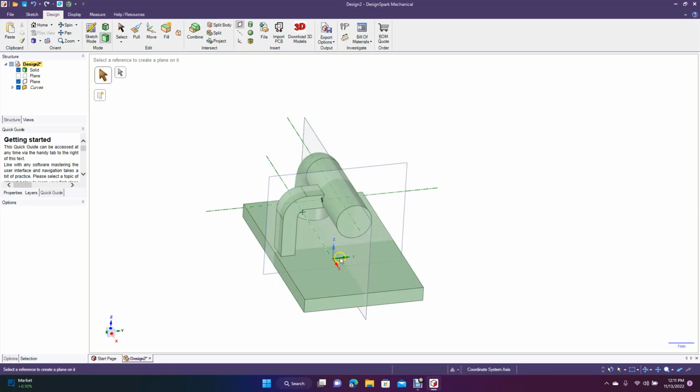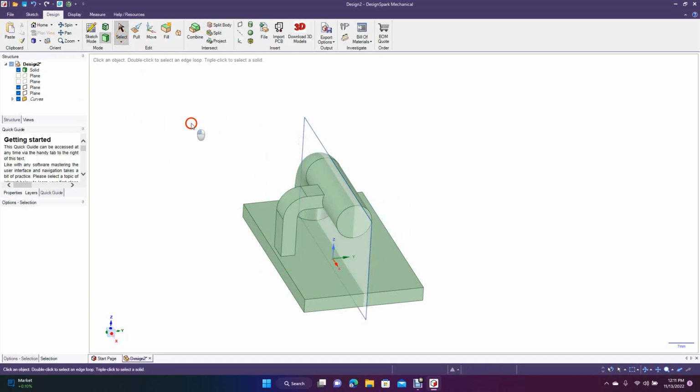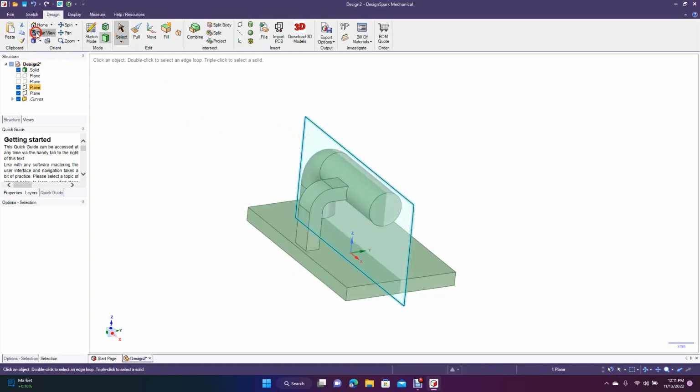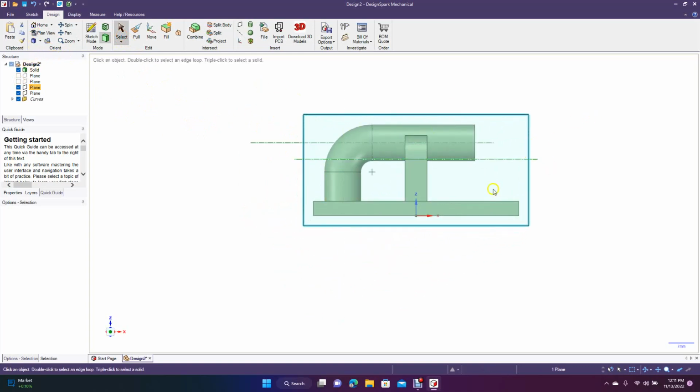So we'll do another one here just so I can show you. Then we're going to click off of this one in the checkbox, and then click on the plane. Actually, let's select, click off, and then click the plane again, then go to plan view. So now we're turning it this way. If we wanted to draw a shape out of this circle and have it come up and wrap around and then maybe go down over here, we could do that.